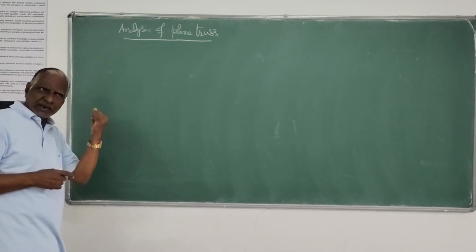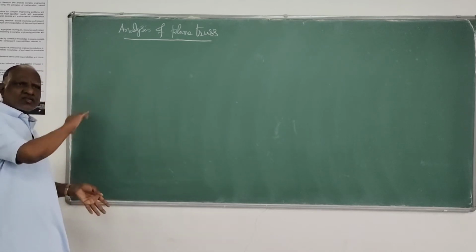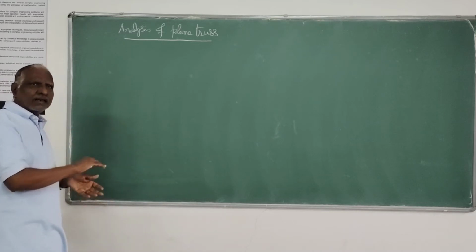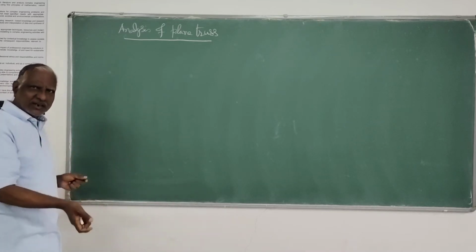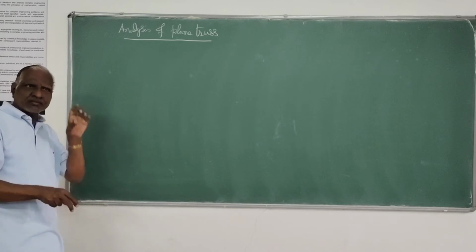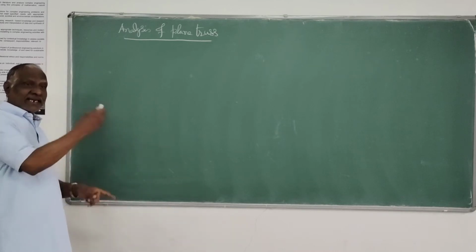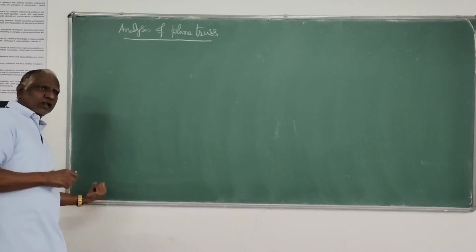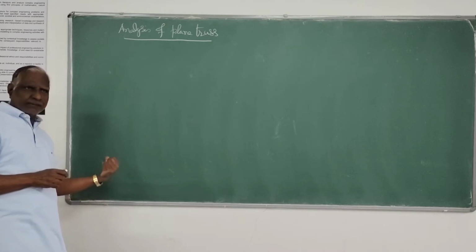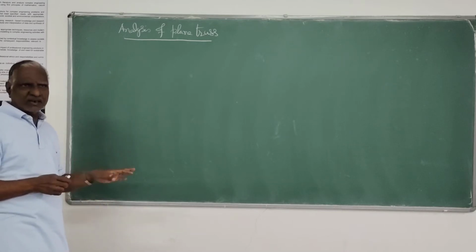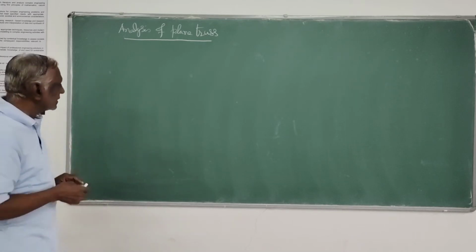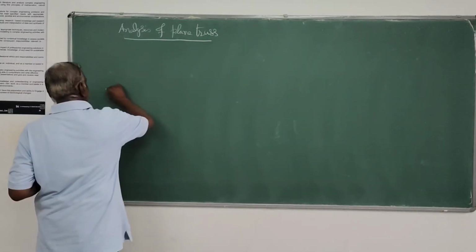First we have to find element properties, then transform them into global properties, then evaluate the unknown displacements in terms of the global axis, then again come back to local member stiffness properties and evaluate the member forces.